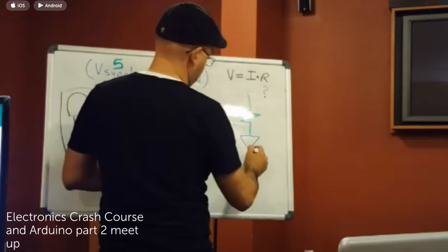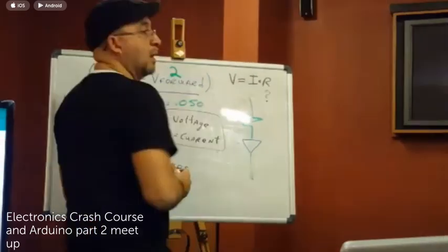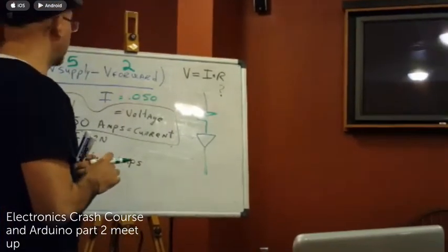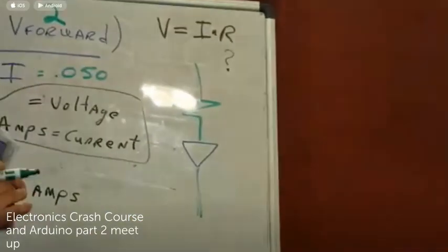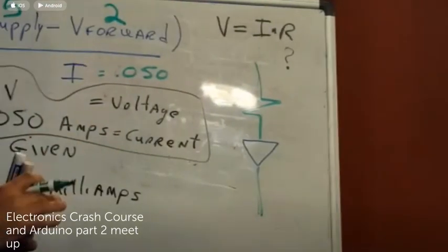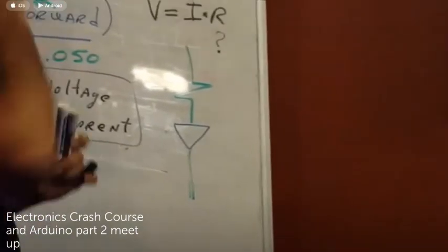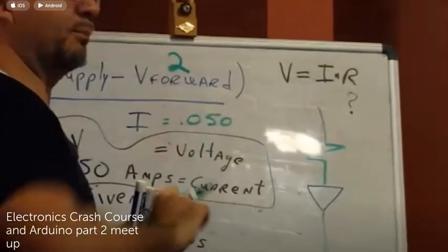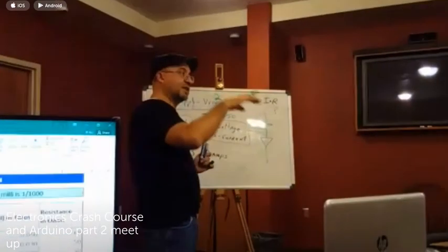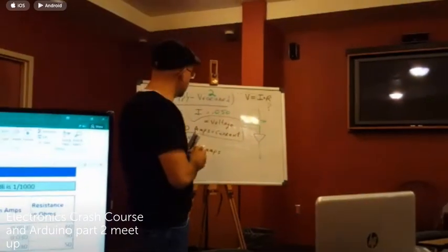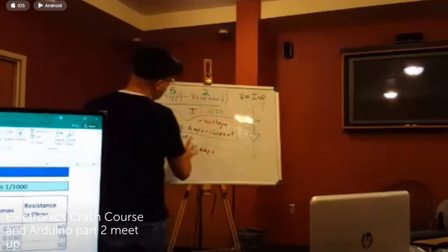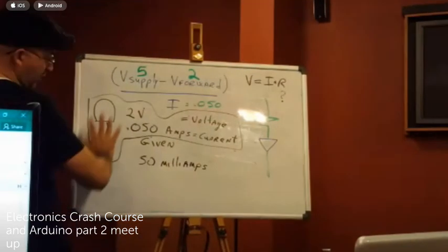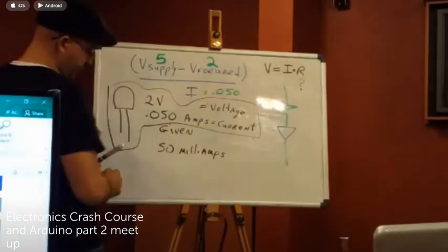What if we use the analog outputs? The analog will not work to create the dimming effect that we're trying to achieve because we're using pulse width modulation, and I'll explain later on what pulse width modulation is. But we're using the digital, and we're making the digital pulse and simulate something like the analog. I see. Yes, so that's what we will be doing. But right now, we're trying to figure out the value of this resistor. We already have it by the calculator, but I want you to see it so you can understand.